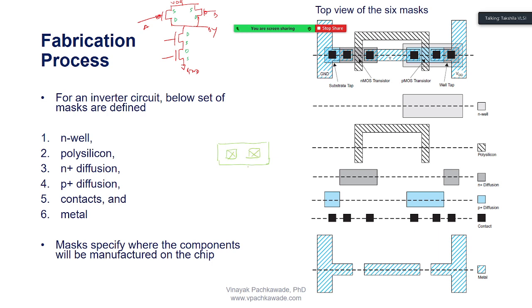These are the contacts, just like shown over here, and there is this polysilicon gate that I am drawing here. Just like here you see that I am not drawing the body of this PMOS. Similarly, there is another N well for which I will draw my transistor, because I need two transistors right here. So I have drawn the layout for this PMOS again. This is PMOS number 1 and this is PMOS number 2, right?